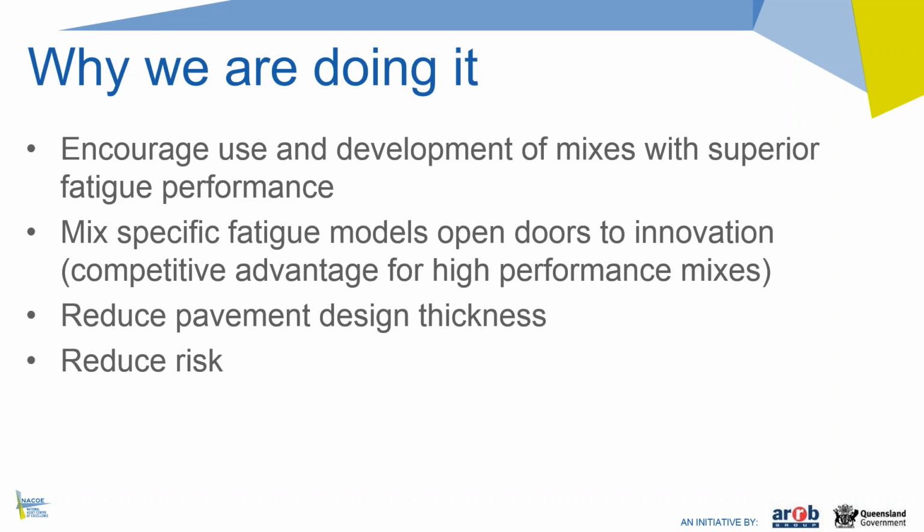Historically, asphalt mixes in Australia have not been optimized for fatigue performance, and therefore you can't expect these mixes to give a much better outcome than what Shell currently predicts. In fact, we have been finding the opposite, except for mixes like EME2 and mixes with polymer modified binder. So it is possible to develop mixes that have a much higher fatigue performance than the mixes we're currently using, and we want to encourage that for use within Queensland.